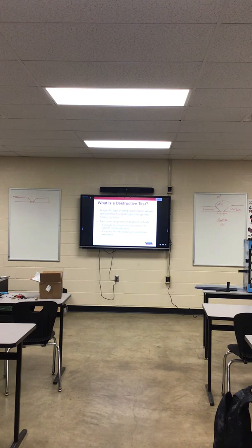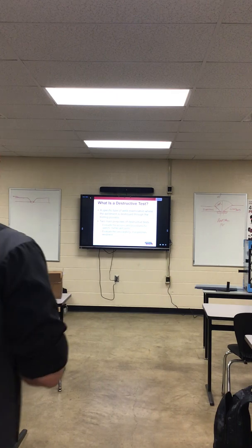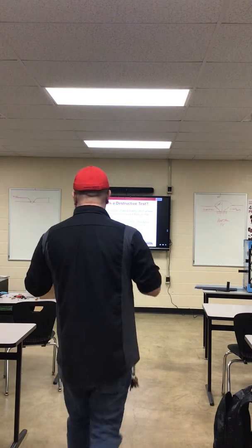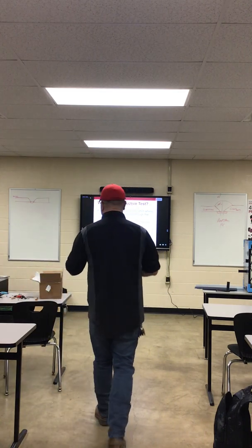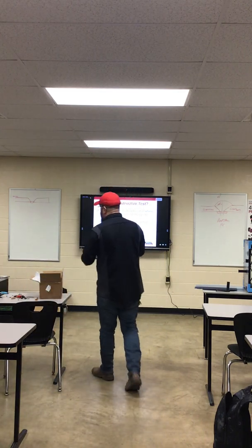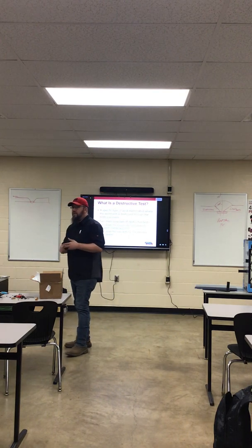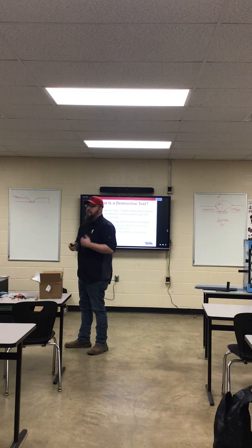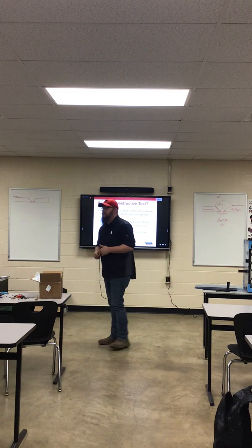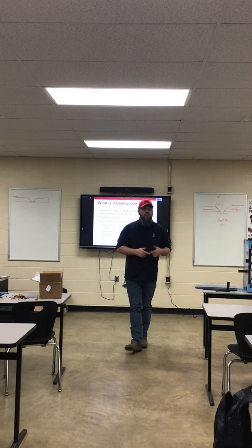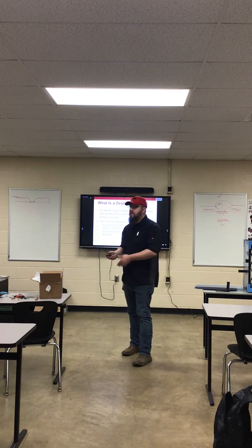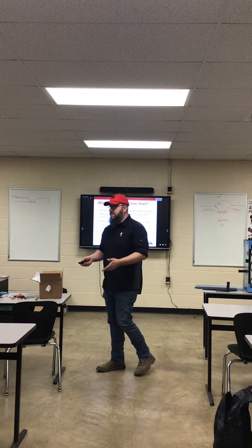Two main purposes: evaluate the processes and procedures for specific metals and joints. So the idea of going through this destructive weld test is you're actually going to understand the characteristics of your weldment, what materials you're using for your base, and what you're using for your filler. What kind of voltages, what kind of amperages are you going to run? How much heat can you put into that material before it hits a critical temperature and fails, i.e. scorching the material?